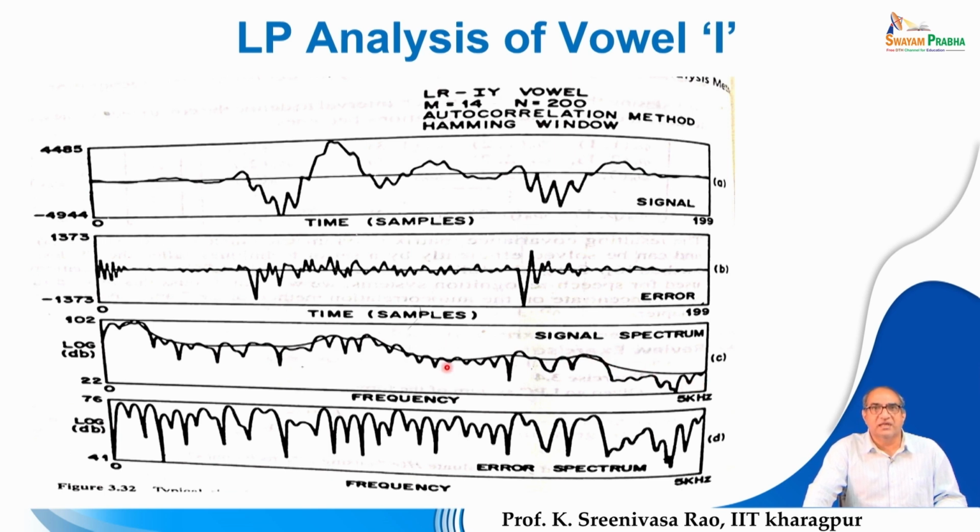That is the reason that the spectrum offered by the LP analysis, or the linear prediction filter, corresponds to the vocal tract, where the spectral envelope almost follows the original signal. These ripples are basically due to the excitation, because, as you have seen, the excitation for generating this particular speech segment is a periodic train of impulses, or periodic pulses.